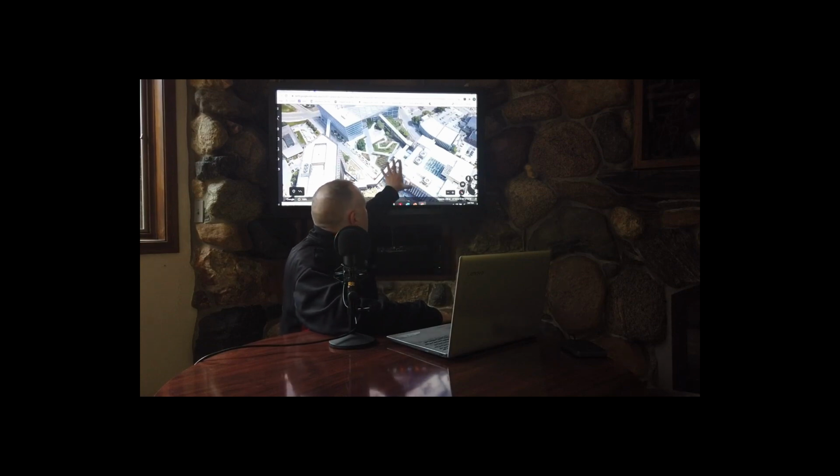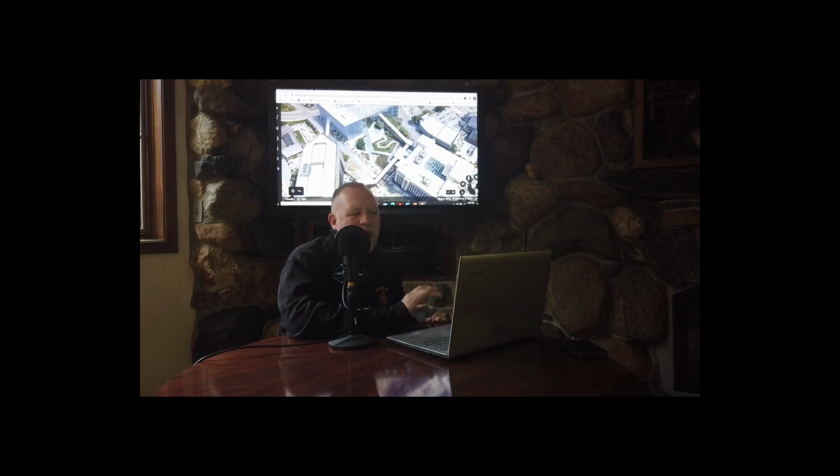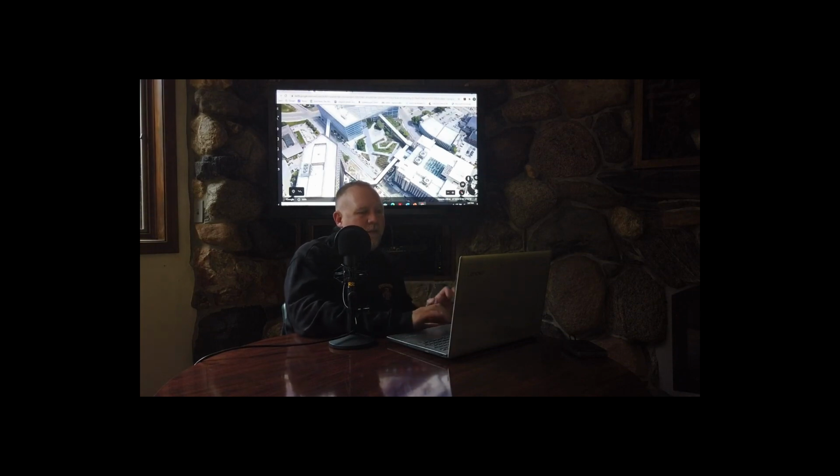The cooling towers for all of this are right here, and the chillers are down in the basement of this building, and they're also down in the basement of this building. There's tunnels that go underneath the streets all the way around there that connect all of those buildings together, and that's where they put their chilled water plant. And plants, I should say it's plural, and also it's where they put all the piping that goes from one to the other to the other.